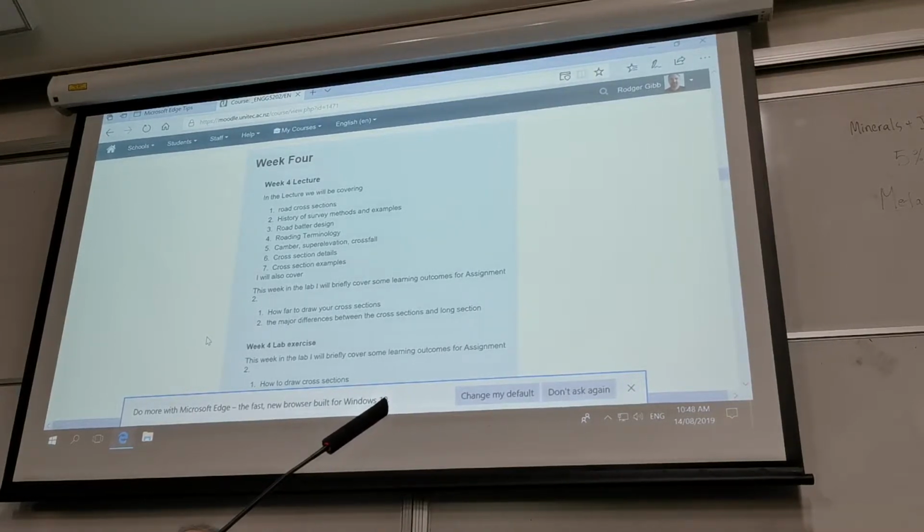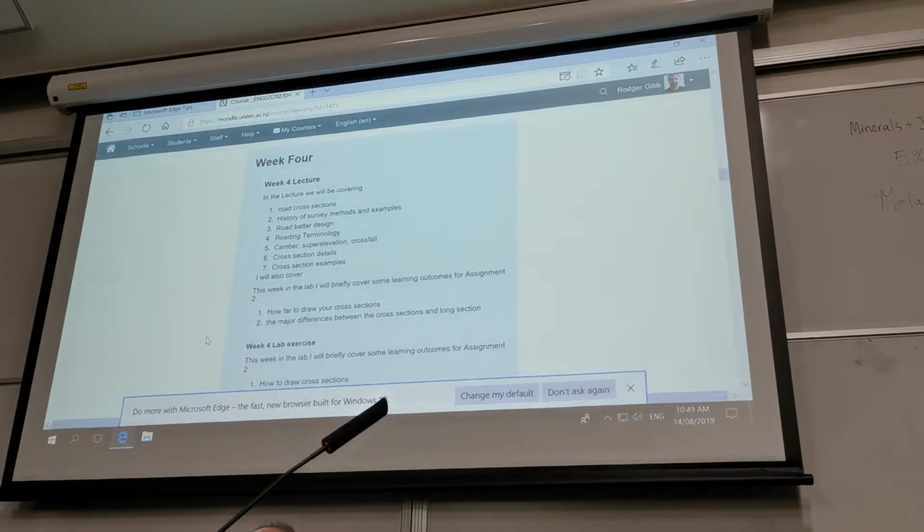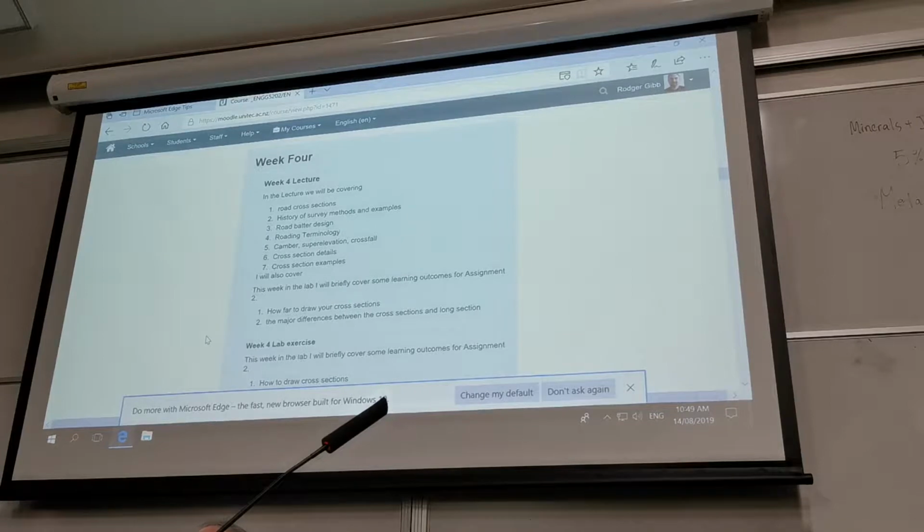Well, as a first hint, if it's curved, you turn it into a P-line and then you divide it into whatever the offset should be, 5, 10, 15 metres, and you can then lay it out nice and flat as a long section like I've drawn. The only difference is Hugh's road's got a curve in it, mine's a straight one. So it's exactly the same techniques, exactly the same stretch technique, everything. But of course, you still get students who have not done this themselves and they will find it very hard in the project. So that's the reason why this is a prerequisite.